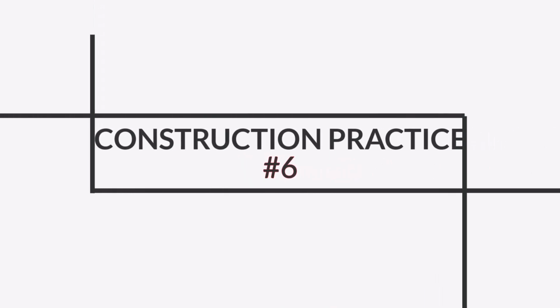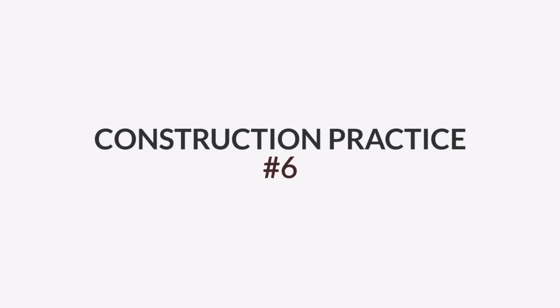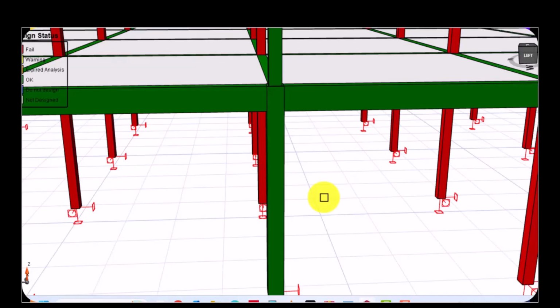The last point I would like to talk about is construction practices. After the design is made, we have standard design practices and standard construction practices. Once these are ignored, with no adequate concrete cover, the reinforcements will be exposed, there will be corrosion, and an increase in the mass of the reinforcements in the columns, causing expansion.